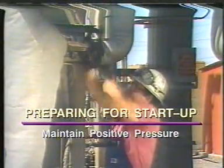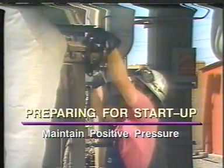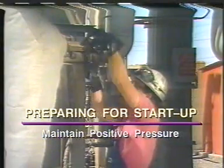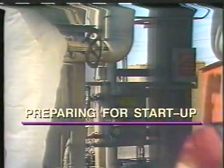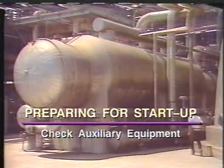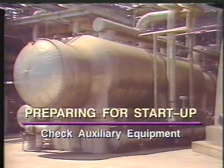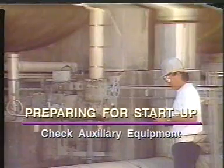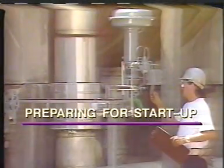After the tower is tested for leaks, the inert gas or steam pressure is released. A hydrocarbon vapor is then backed into the column to avoid pulling a vacuum. Before starting the tower, make sure that all auxiliary equipment like reboilers and condensers are ready for operation. Also, make sure that any water that might have settled in low points has been drained out.